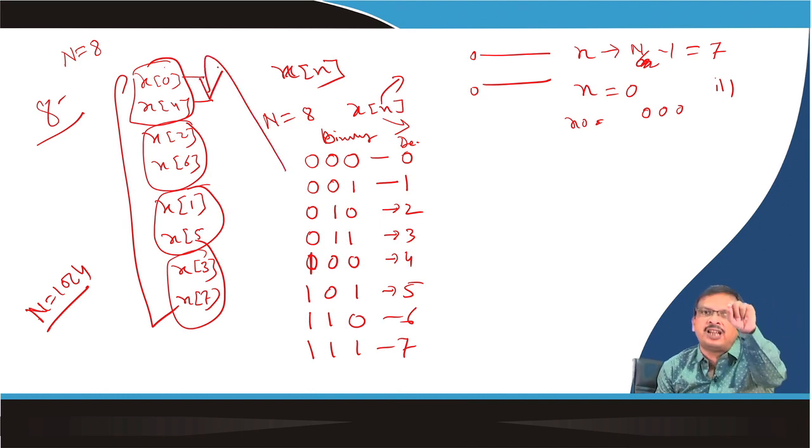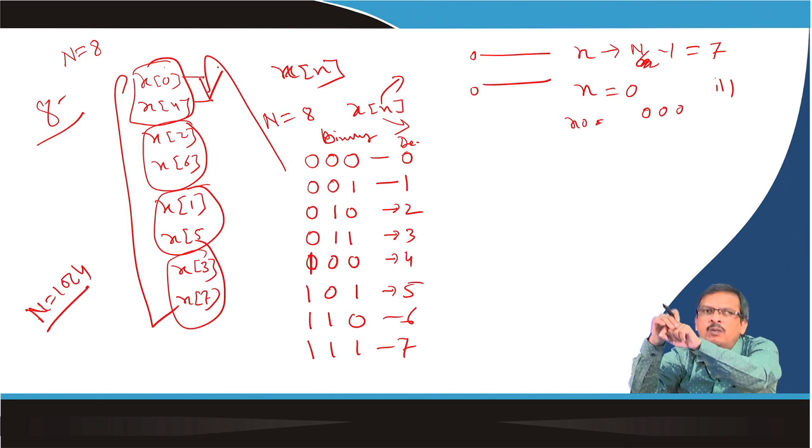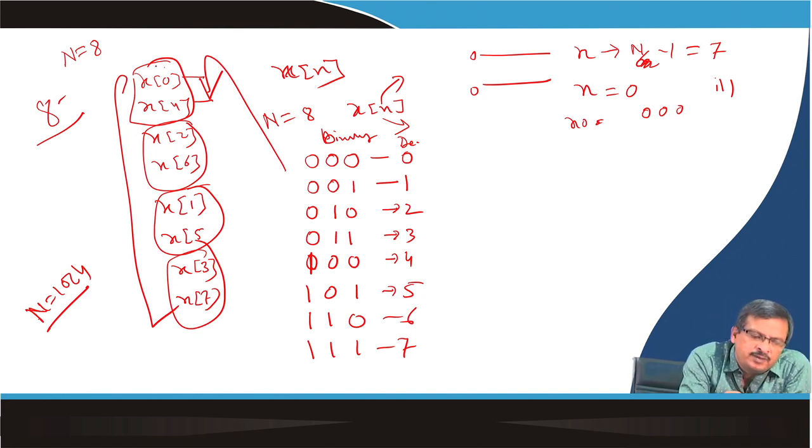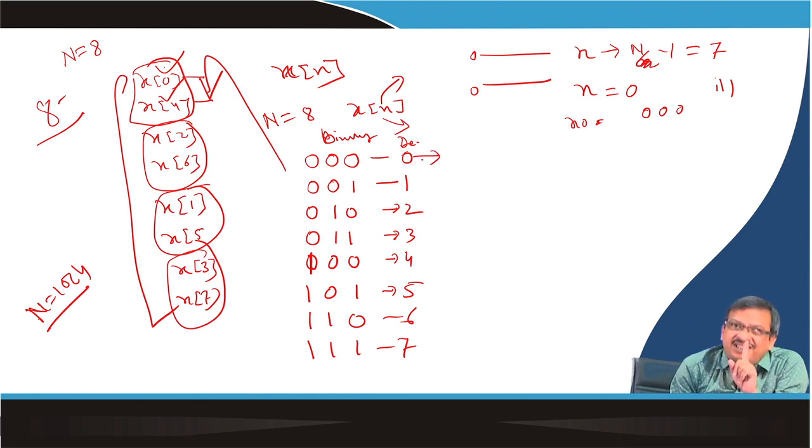First the 0th sample, then the 4th sample, compute the butterfly, then the 2nd sample and the 6th sample, compute the butterfly. So, how do I decide my accessing sequence so that I can club the 0th sample with the 4th sample? It says that if I access the index in bit reverse mode, so this is B1 bit, this is B2 bit, this is B3.